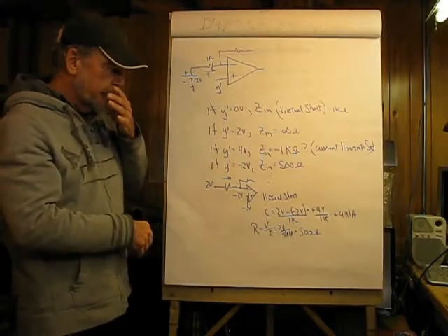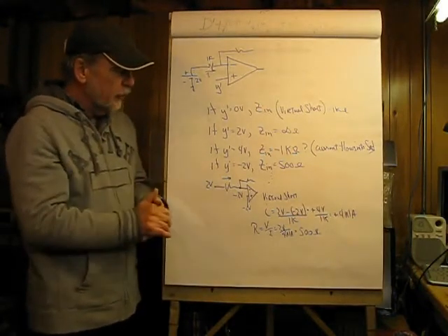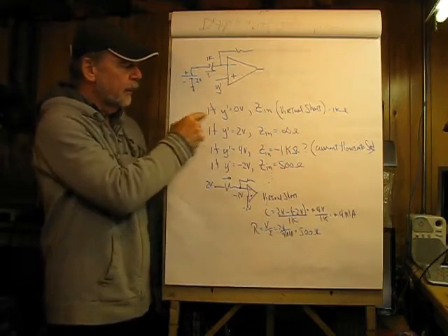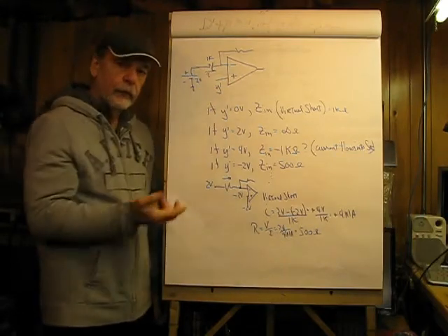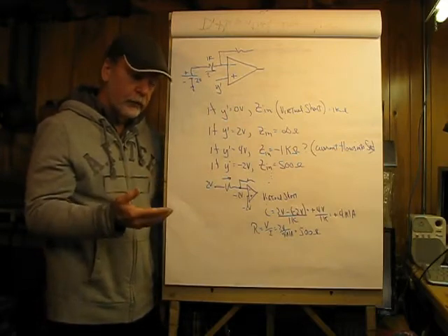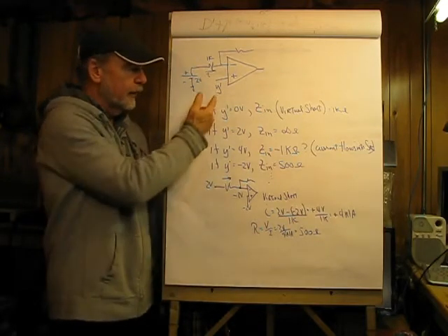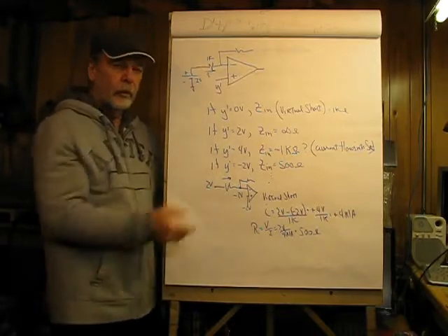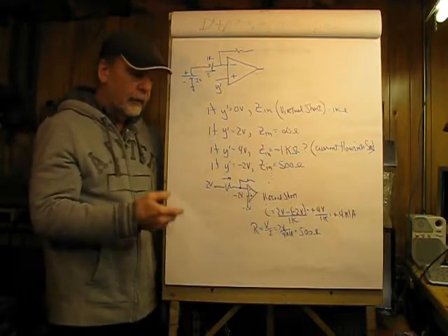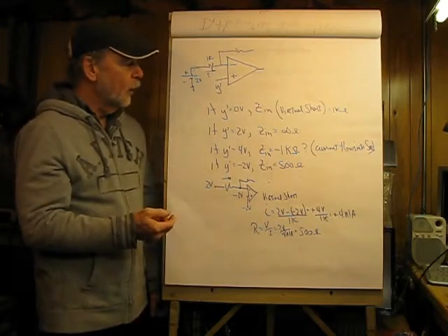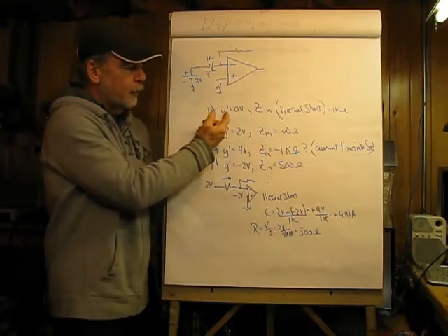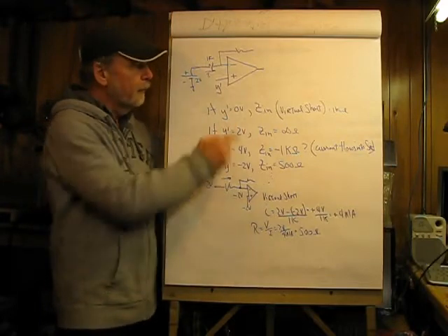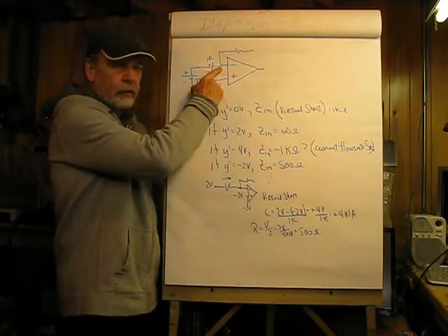So if we take a look at this specifically to see exactly how bad this can be, and what I'm using here is Y prime. I've not bothered to include the resistors in the circuit, just saying that's the voltage of interest. I'm letting the source be 2 volts with an input resistance to the non-inverting input of 1K. So if Y prime equals 0 volts, due to the nature of virtual short, that means that this node right here is 0 volts.